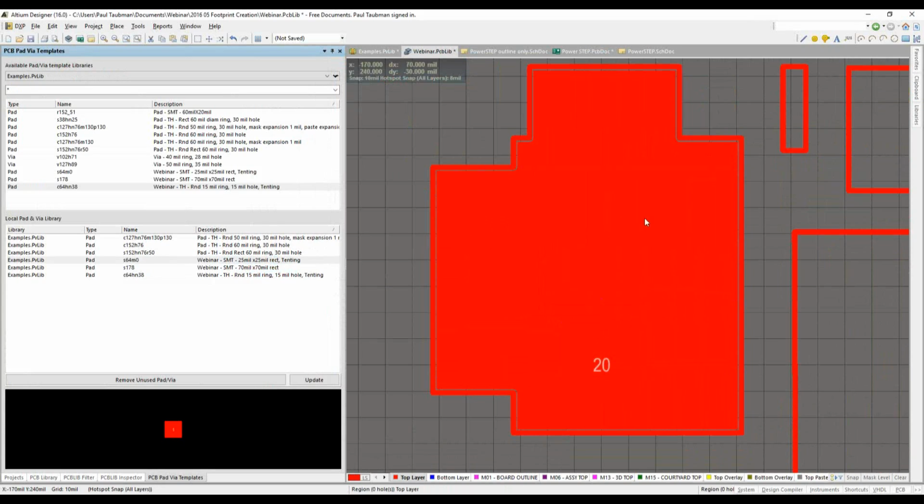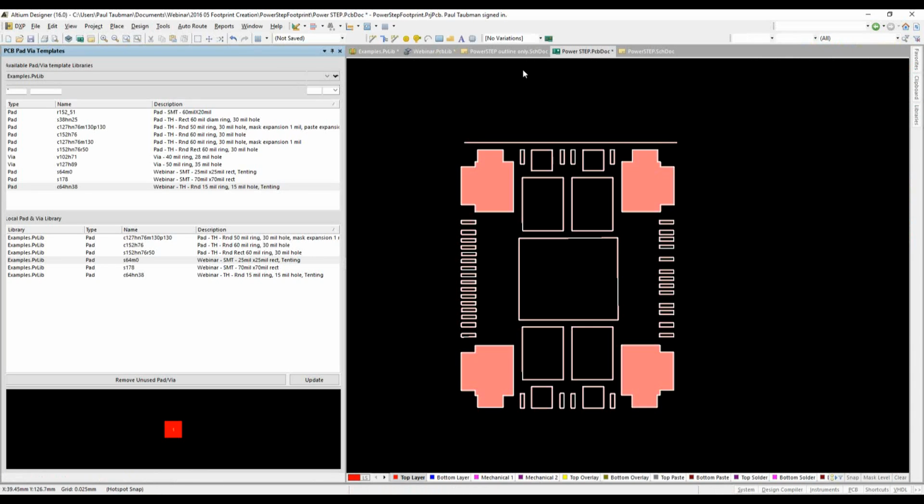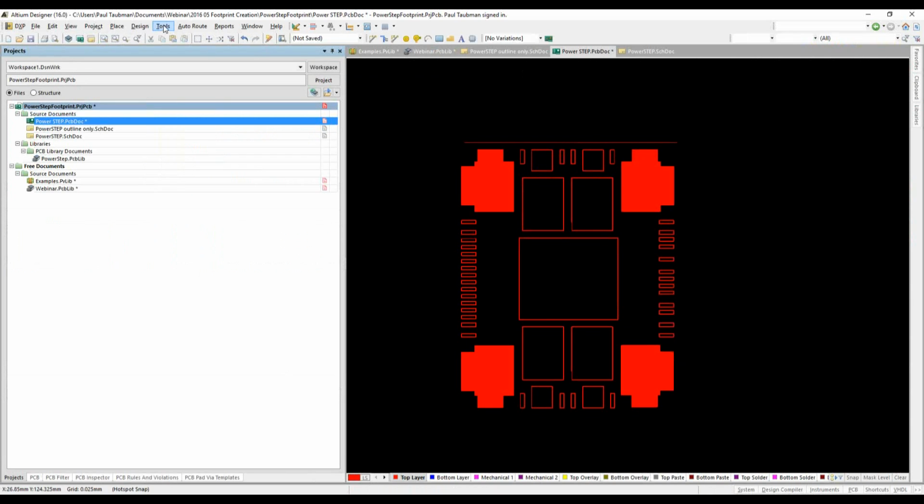And Altium will recognize the 20 here, and it will associate the pad to the pin. Lastly, what will happen is that when you go through the process, you link up the symbol, you put this into your schematic, and then you push it over to the PCB. It will show as a short because the rest of this will be a no net, but pin 20 will actually have its net. So there's a really nice feature Altium has, just to make note of it.